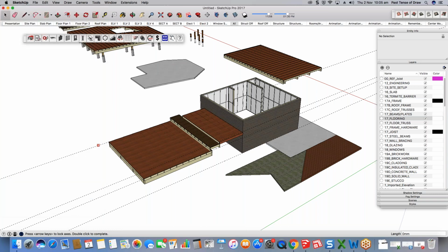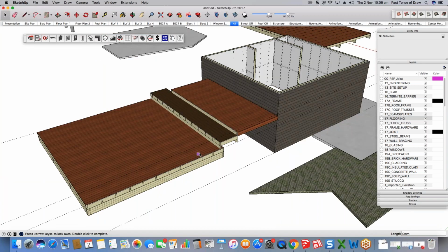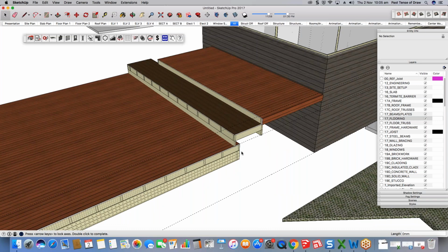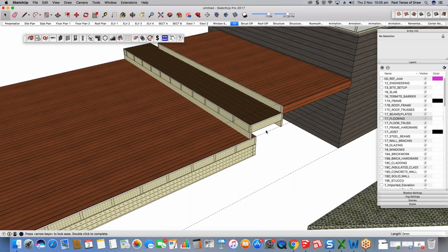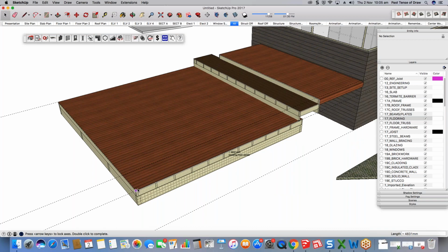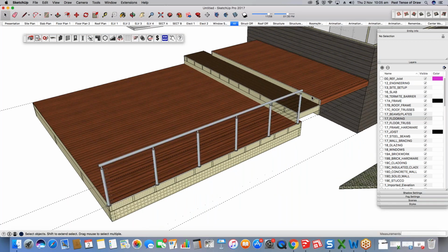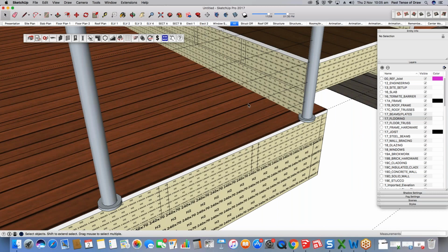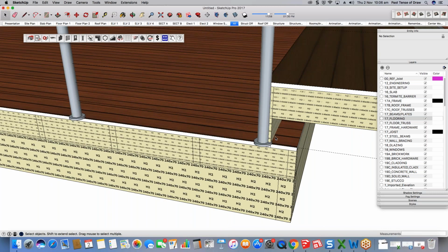Press submit. And then what you're able to do is simply, again, I would be going into structure if it's going to be on my structure. If it's going to sit on my finish, then I'm not. I'm just going to have it sitting on my finish. And now that I've placed it, understand where it places it from. Again, it's important. If you need to set a setback, then it's good to do that with a guide, because wherever you draw the line is where it's going to draw from.